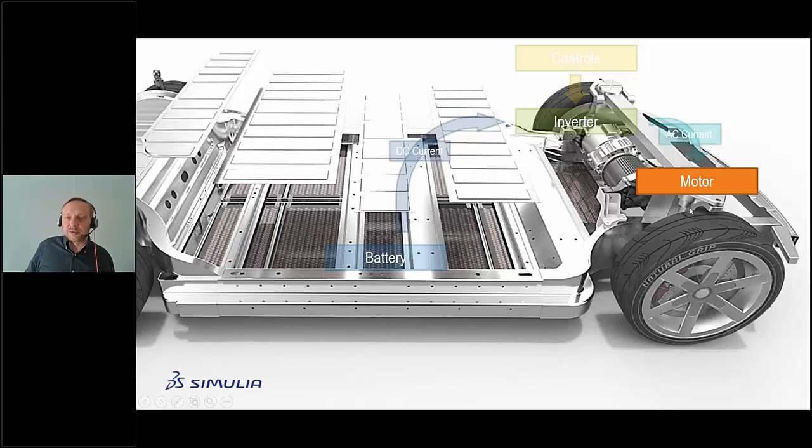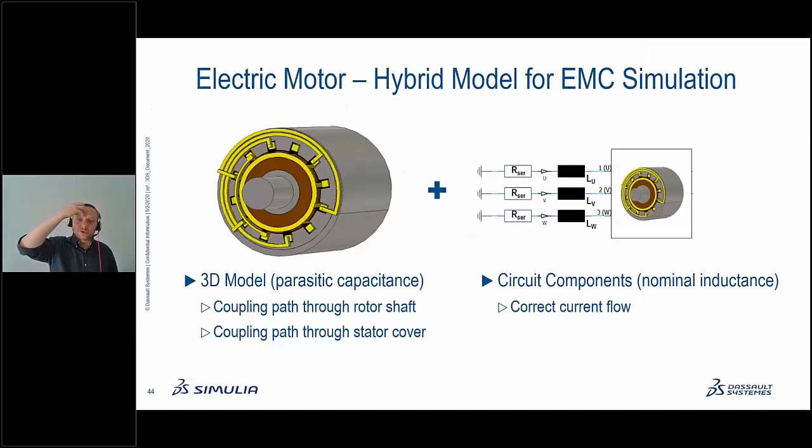I mentioned already in the beginning, in the inverter simulation parts, we have used a very simple motor, basically 3 inductors on the schematic, but that's pretty simple. And what we want to build is, of course, a more advanced model of the electric motor, but not a model which is used for force calculations. The people who are designing these motors have a very strong interest in the force, because that's the creation of the torque of the motor, and in the losses. These are the key points for a machine designer, while for an EMC engineer, the key points are different.